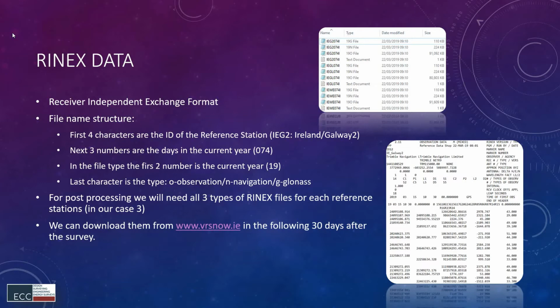Just make sure you have the RINEX data for the correct time, even an hour earlier and an hour later, because I'm always confused with summer and winter time, so just add an extra 2 hours. So let's say you went out at 9 o'clock, started the survey and finished at 3 o'clock, then just download everything from 7 till 5. It's a little bit bigger file, but at least you have everything covered.